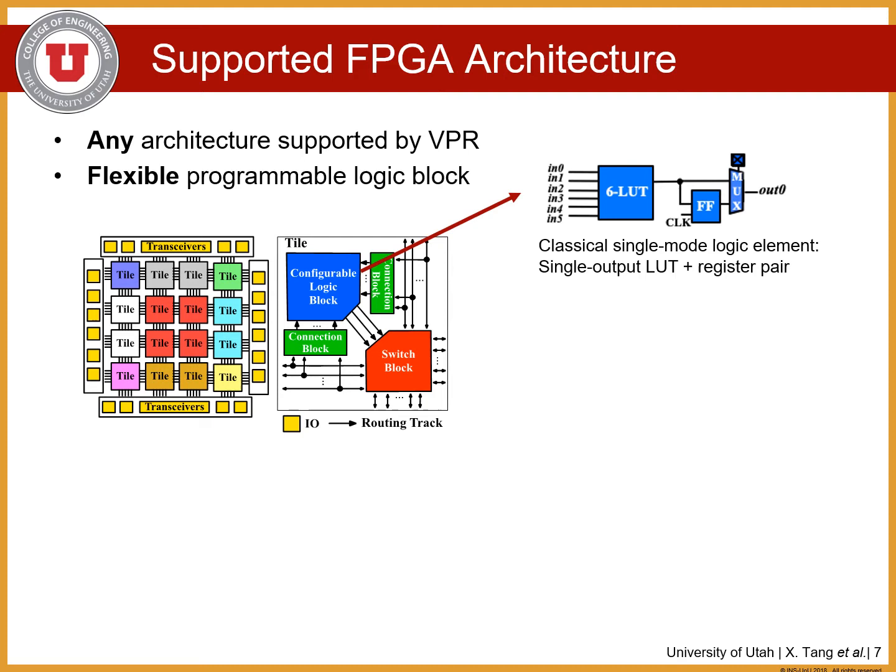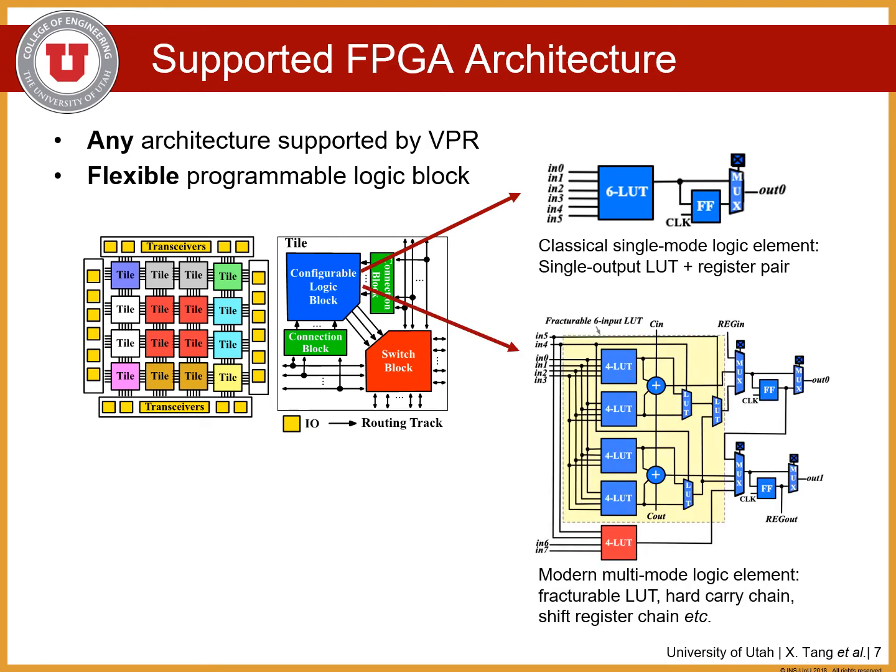In the programmable logic block, we allow users to define, for example, a single-mode logic element, as well as a multi-mode logic element, capturing the most advanced logic element design in Xilinx and Intel, these cutting-edge FPGA devices.